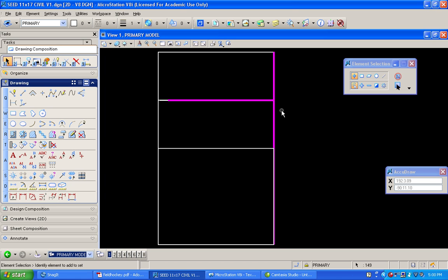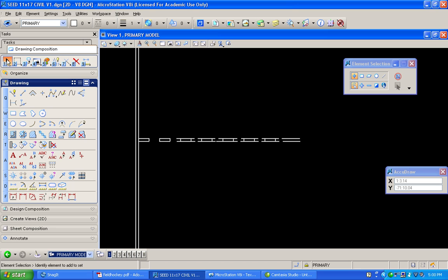So if I've got a gap and I'm actually going 2 feet, half of 180 would be 90. So let's copy this one 90 times from, again, this point to this point. It should pretty well cover it. And we just went over just a little bit over here, so we can take those out.